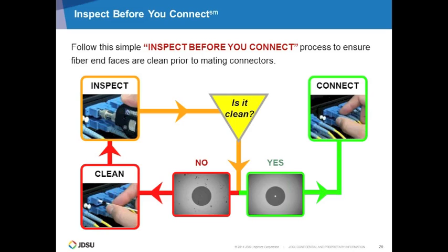Third thing is, what if that connector is damaged? That connector, before it was handled by you, was probably handled by someone in manufacturing, then system integration, pulling the cable. So probably you're the fifth or sixth person who's touching this fiber. I personally don't believe that everybody before me followed the right procedures and that I know that the fiber is clean and not damaged. It's better to be safe and not assume someone else's mistake.